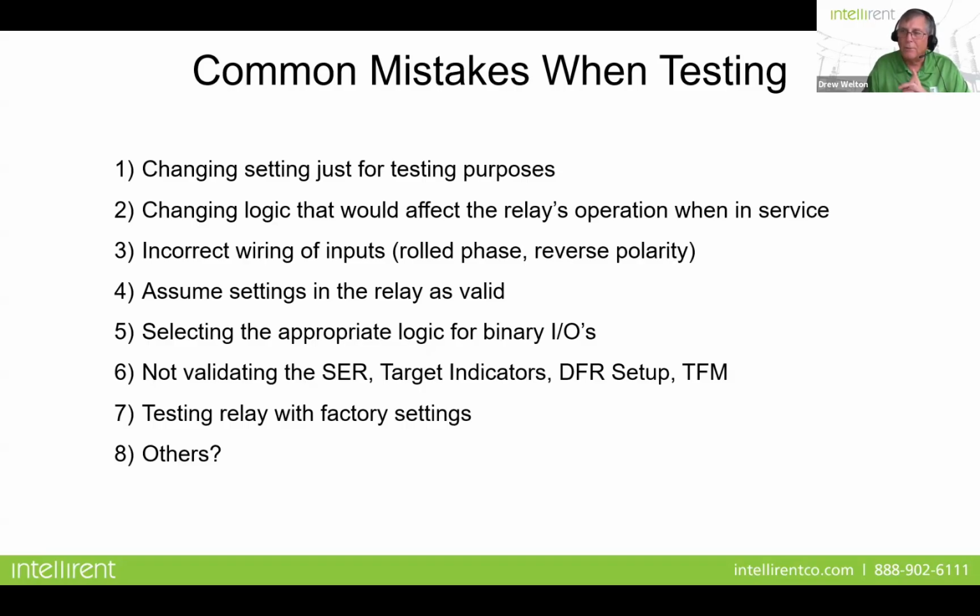One other thing that I think is important, we talked about this a little bit, and that is the through fault monitor in the relay. You really want to make sure you enable that through fault monitor, because if the relay has seen a number of through faults going through the transformer, when you go out to do maintenance testing of that transformer, you may want to check that you haven't incurred any mechanical damage, because a through fault actually puts mechanical forces and stress on the windings of the transformer, and over time these through faults can create damage in the transformer, and you may not find out about it until it's too late.